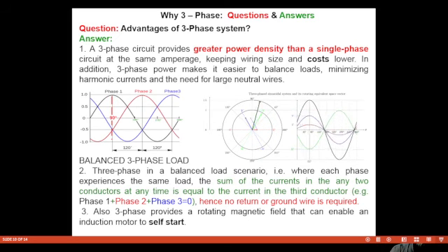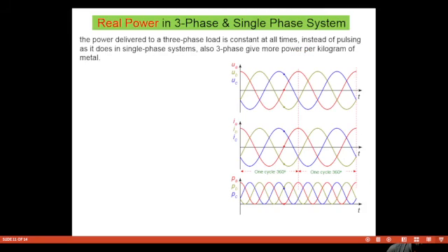So when we connect the three phase to the stator winding, we get a similar type of rotating flux, which induces flux into the rotor bars of the induction motor, which are shorted. Because of that, current flows, and because of the current, flux flows, so we get two fluxes: one the rotating flux in the stator and the other flux in the rotor. Because of the interaction of these two, the rotor of the induction motor starts rotating in the direction of the synchronous flux.